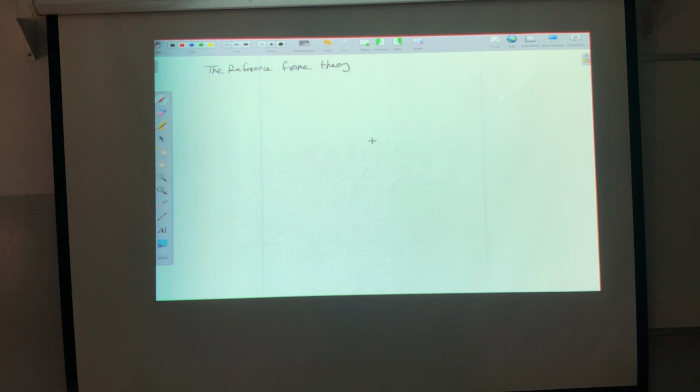Now, to make it simple, let's assume that we have a three-phase stationary system. So this is the AS, and this is the BS, and this is the CS. Those frames can describe any stationary cell, the stator. The stator is stationary, correct? So with respect to the stationary reference frame, all the quantities are alternating. The current is alternating, the voltage is alternating, and the flux is alternating, correct?